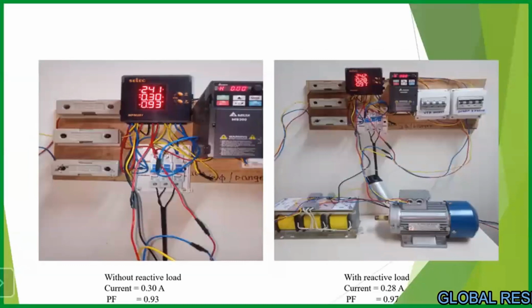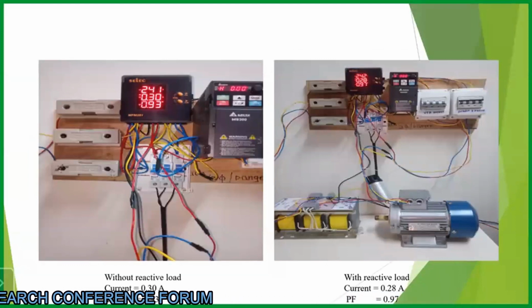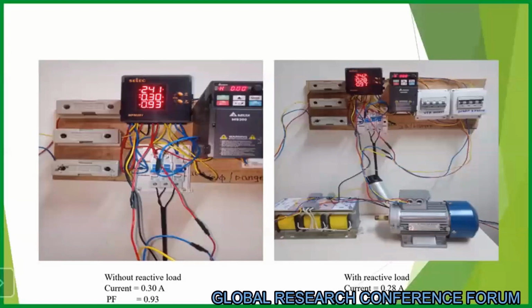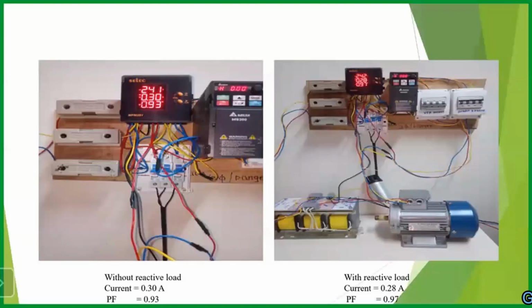Here are two diagrams. The left diagram shows a phase to neutral voltage of 241 volt, a current of 0.30 ampere, and a power factor of 0.93. Actually, the load is running in dry condition, so it has a 0.93 power factor. If the load is under load, then the power factor falls down to 0.7 also.